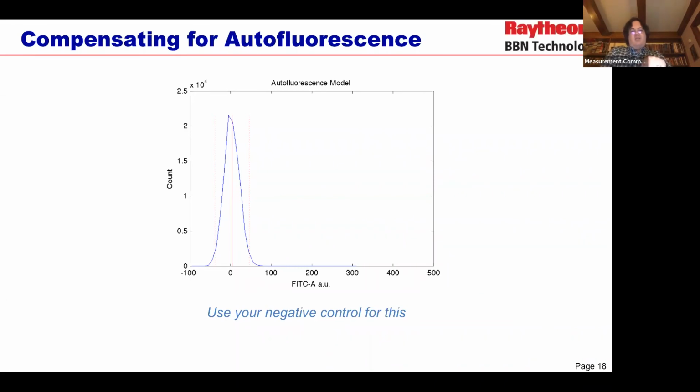So we're going to end up subtracting just a couple units. And this also tells us where is the minimum level that we can rely on a number. Once we start getting down into the instrument range, in here, any measurement less than about 50 should be considered suspect, because at that point, we're really getting entangled with instrument noise.